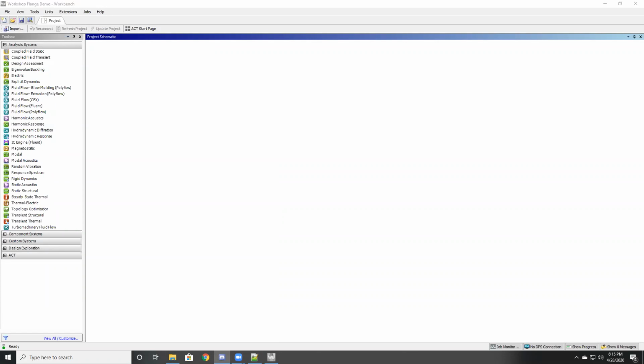It is a step file. When you're working with Ansys, first thing is do not use the built-in CAD program SpaceClaim. It's terrible. I made this with NX, and it can take NX part files. However, it's even easier to import step files. Sometimes the part files you have to reopen in SpaceClaim, and since SpaceClaim is so bad and takes so long to boot up, you want to avoid using it wherever possible. So I've sent a step file there. You can do that in NX by either exporting as a step file or saving as a step file. Either is fine.